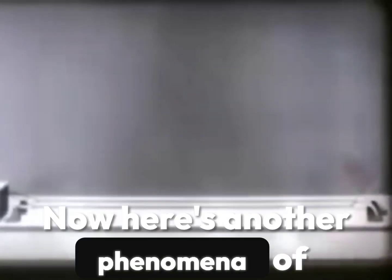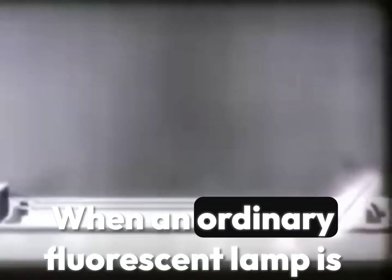Now here's another phenomenon of resonant transmission lines. When an ordinary fluorescent lamp is placed near the line, it can be used as a voltage indicator. When the tube glows the brightest, it indicates a point of peak voltage in the line.